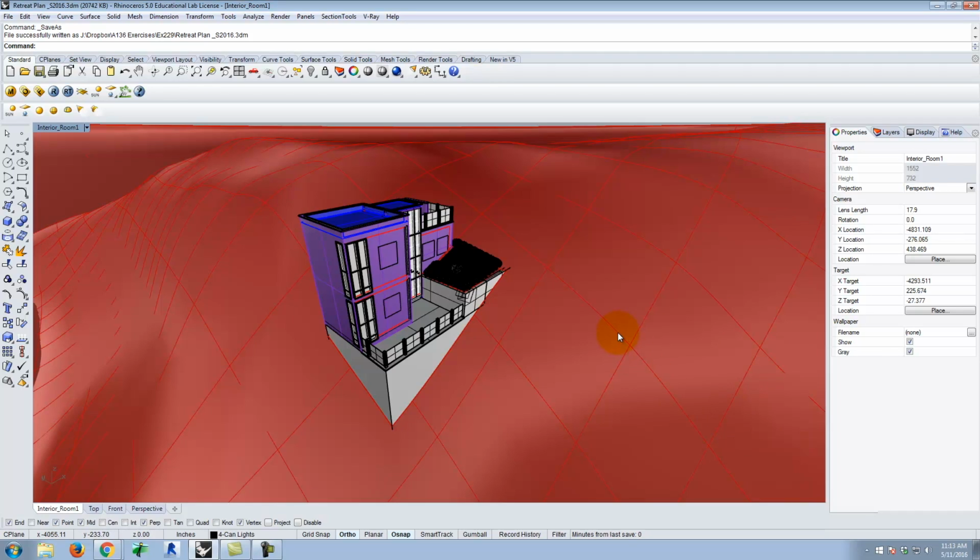Okay, so now when I create a plan view, we cut our plan view at 4 feet above the floor so that we cut through all of the windows. We cut through the doors, obviously, but we're cutting above where the kitchen counters would be, so we're seeing down and seeing kitchen counters. If you had a furniture plan, we'd see the furniture in the plan, that sort of thing. So when I make my cut today, I have to think about where do I want to cut through my building, at what floor do I want to cut through my building, what's appropriate.